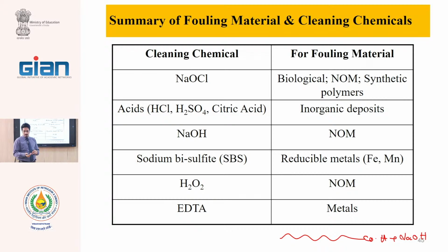the soap. Sabun, you say sabun? In Iran, we also say sabun. This is the reaction of the NaOH with NOM. NOM, most of them similar. The structure has this fatty acid. Therefore, when we add NaOH, it reacts with NOM and produces sabun, and sabun can be easily washed from the membrane surface.